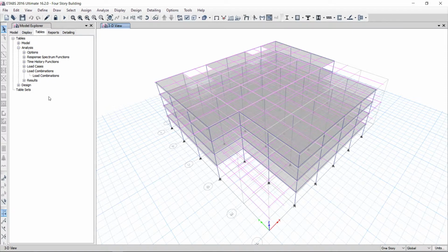Maybe they thought that this is a more conservative approach, so why should I take 0.5L? Very good answer, but in some cases, it's a better idea to have 0.5L where your live load is excessively high, otherwise your structure will not be very economical.